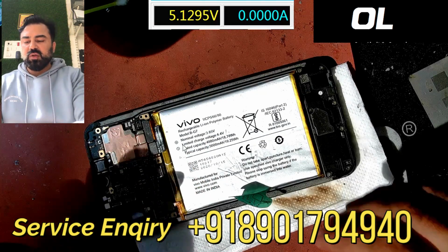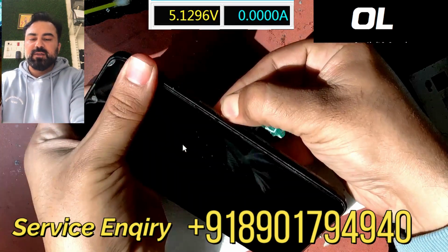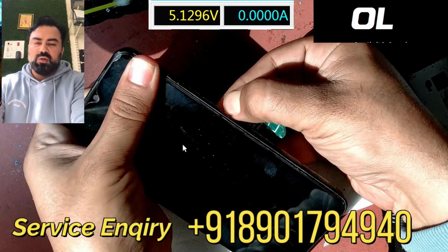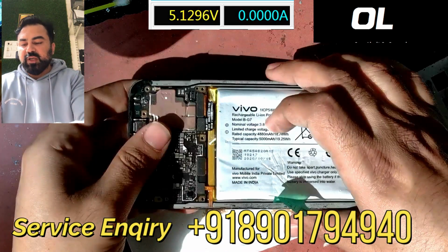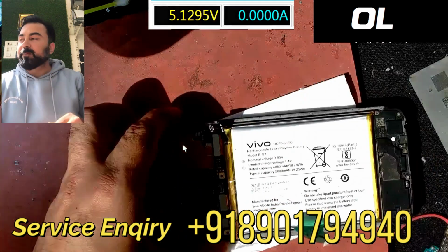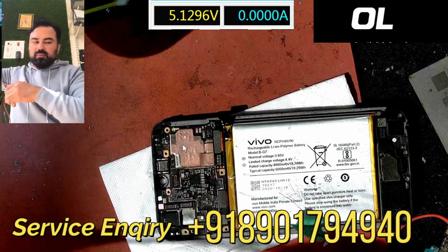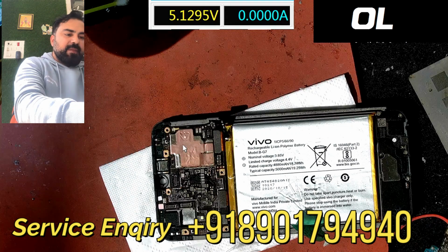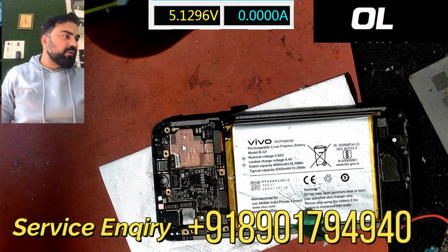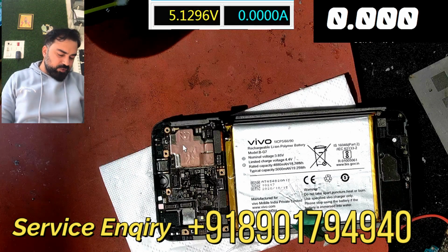Right now, let me try to turn it on, and it doesn't boot. Nothing, no symptom. Now we check the battery, measure the battery voltage with the multimeter on DC voltage mode.